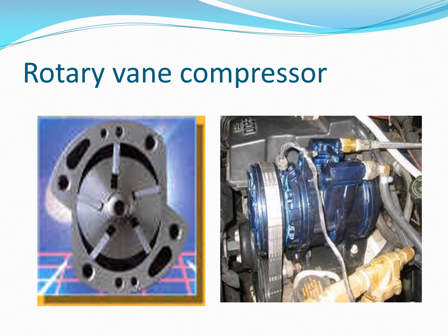So one side of this, if you're looking at the picture in front of you, the upper area might be compression on one side or intake on one side and discharge on the other. So as that vane crosses over from the intake side to the exit side, it is taking the refrigerant in and then compressing it as it moves to the exit side on both top and bottom.